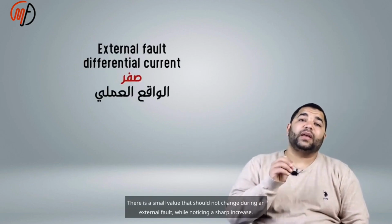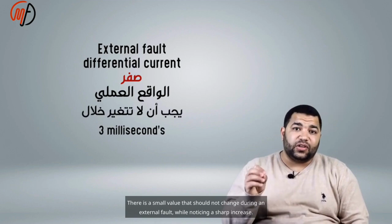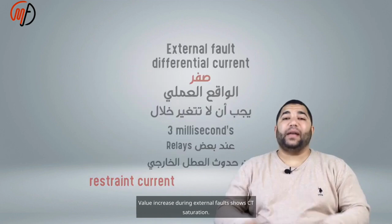There is a small value that should not change during an external fault, while noticing a sharp increase in an internal fault, where both values rise together. A time delay between their rises is crucial. A value increase during external faults shows CT saturation.